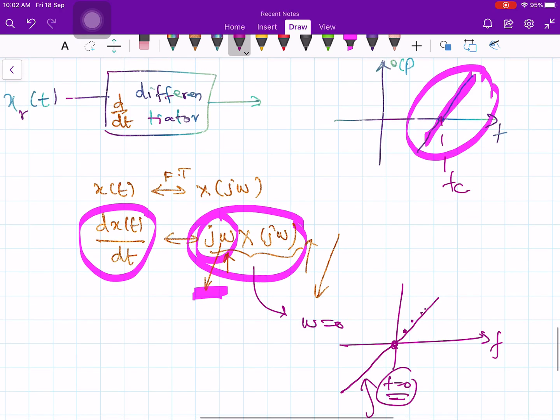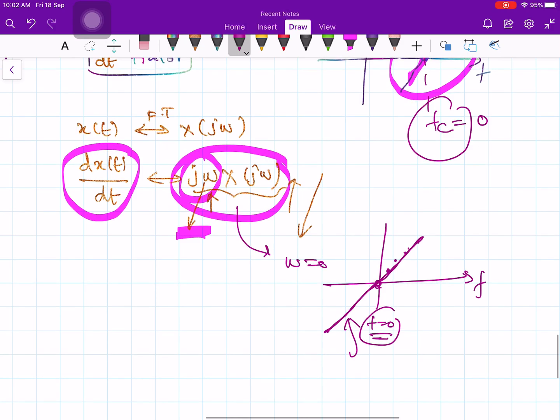Therefore if you take a differentiator, you can get the linear characteristics like this with certain slope, but centered around where frequency f equals 0, but here it is centered around the carrier frequency. So that is the only difference. Okay, so the differentiator output is centered around the 0 frequency, and at frequency 0, the output is 0.